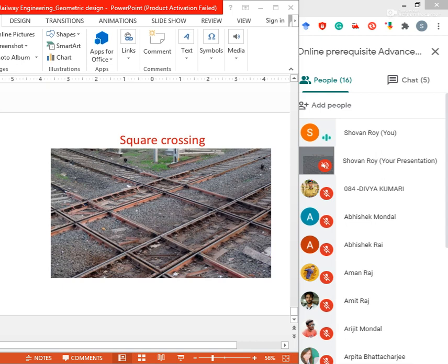Normally, as you can see in your book also, a railway station is that place on a railway line where traffic is booked and dealt with, and where trains are given the authority to proceed forward. Sometimes only one of these functions is carried out at a station, and accordingly it is classified as a flag station or a block station. In the case of a flag station, there are arrangements for dealing with traffic, but none for controlling the movement of the trains.